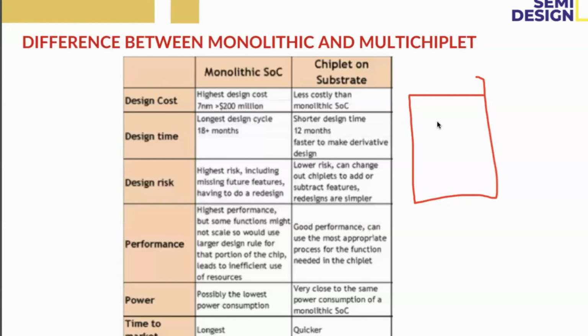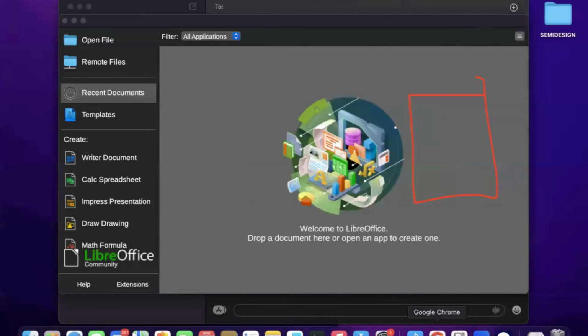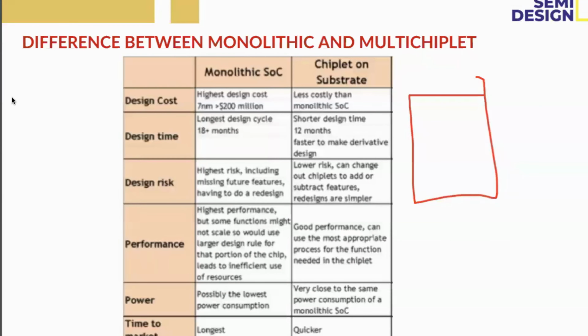Suppose RISC-V has some architecture and CISC has some architecture. RISC-V mainly depends on the pipeline, the number of stages like fetching, decoding, executing, and memory. Based on the pipeline, we will write the instructions. Suppose how will the RISC architecture look? First, we need to fetch the instruction. It will be byte addressing for RISC-V, right? So it will increment by +4.